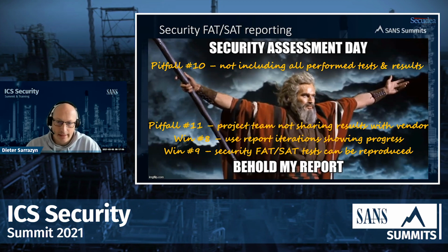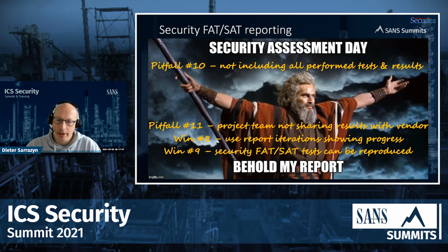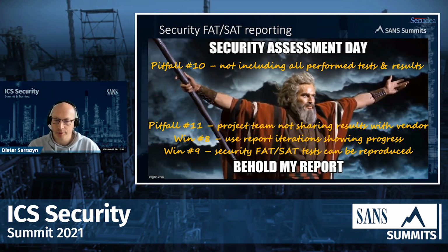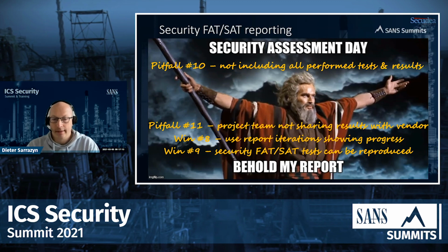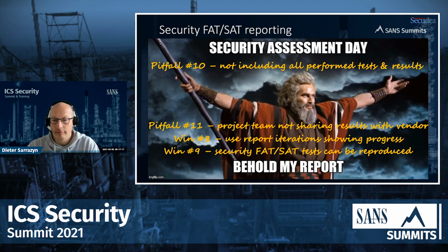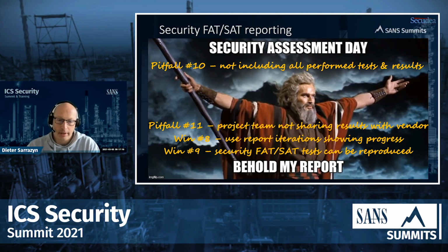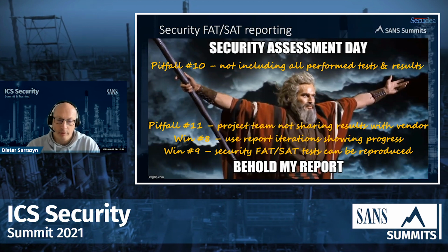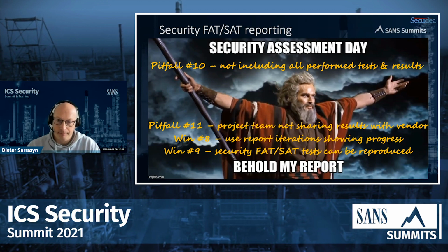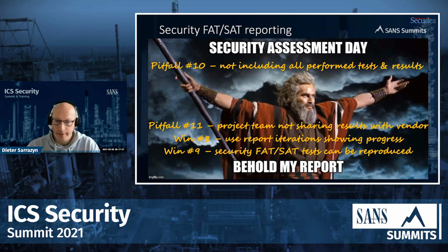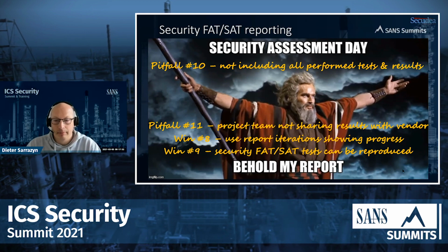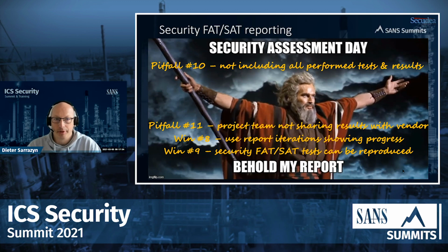The win here is that if you use the report iterations showing the progress, so the report of the FAT, you use it again to report the SAT things, and you show the progress. That's a big win for your customer as well, and for the management of the customer. And another win is that security FATSAT testing can be reproduced, because it's not always you who will be doing the same testing all over again. So that's also something to keep in mind when doing cybersecurity FATSAT testing.